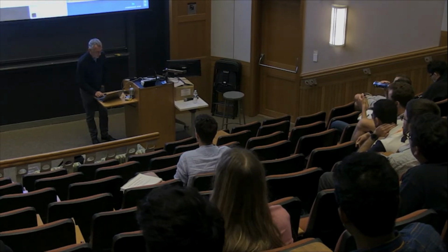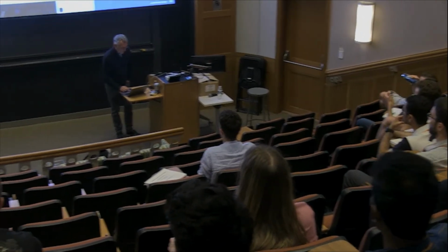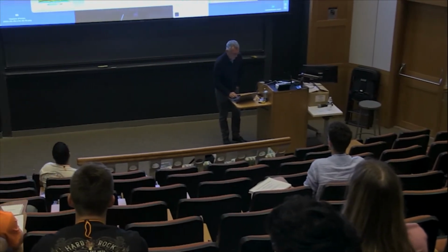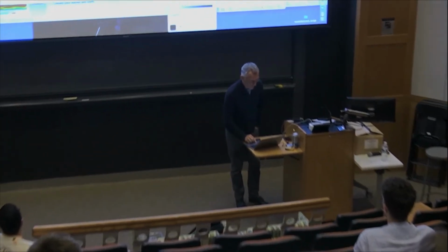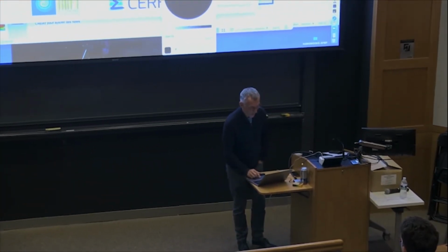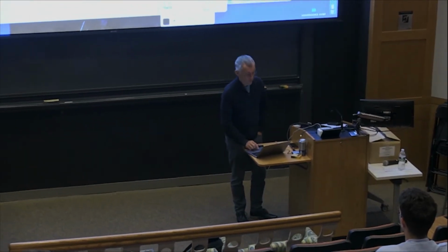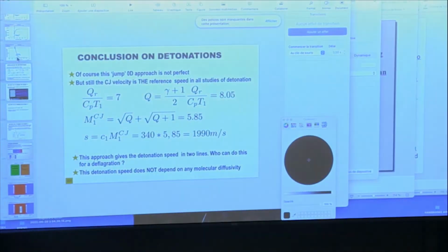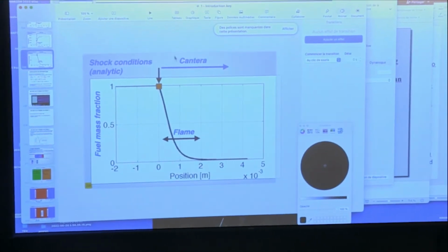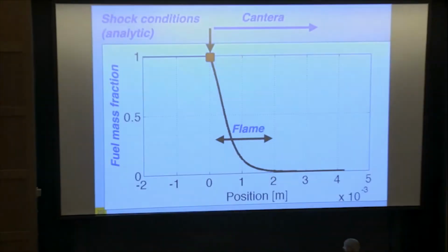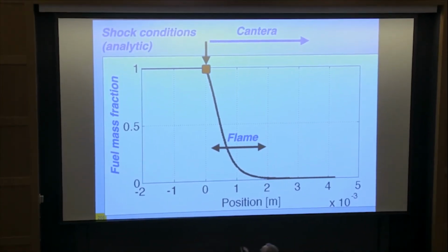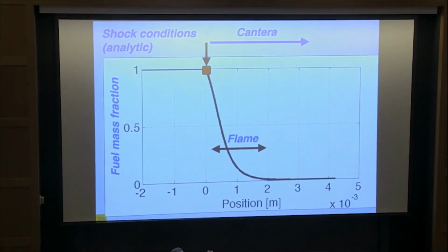Yeah, the induction zone is exactly the one I've shown here. Just after the shock, you have a moment where those gases are hot, and so it's a little bit like an autoignition problem. You start, it takes a while. You start combustion. This is here. And the induction length is basically the time it takes for combustion to start. And actually, this is the flame thickness somehow.